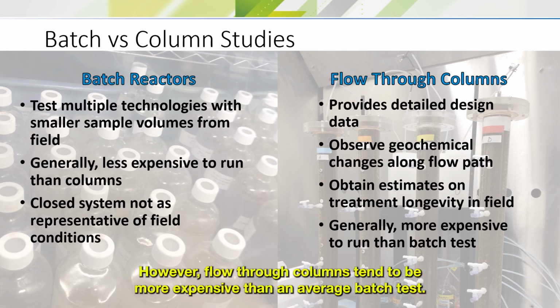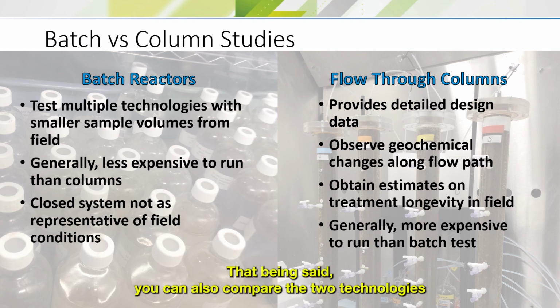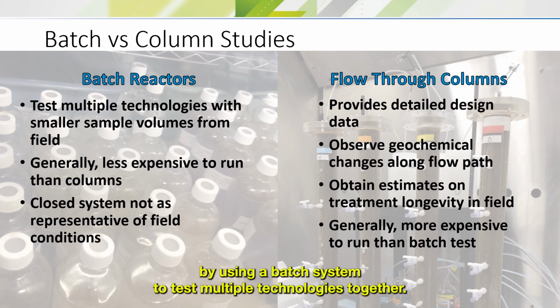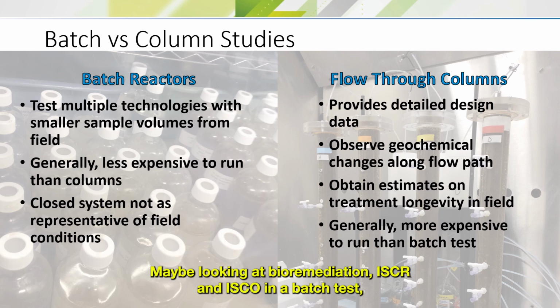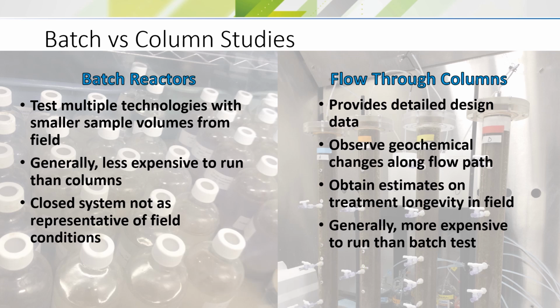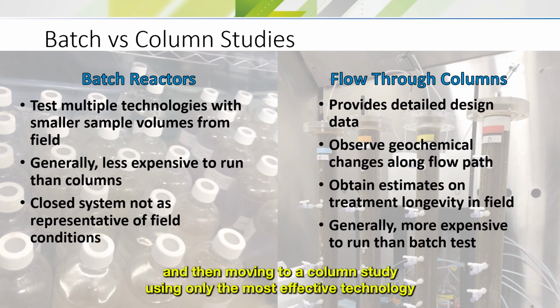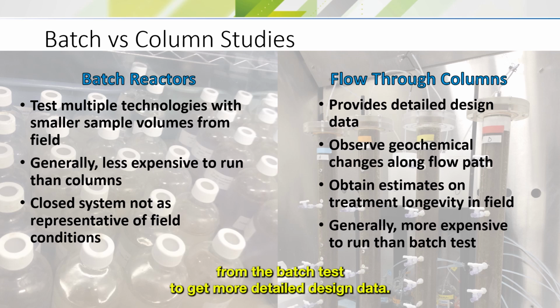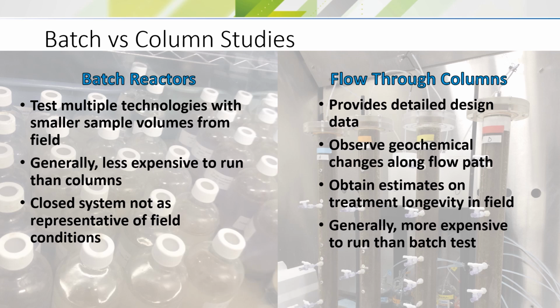However, flow-through columns tend to be more expensive than an average batch test. That being said, you can also compare the two technologies by using a batch system to test multiple technologies together, maybe looking at bioremediation, ISCR, and ISCO in a batch test, and then moving to a column study using only the most effective technology from the batch test to get more detailed design data.